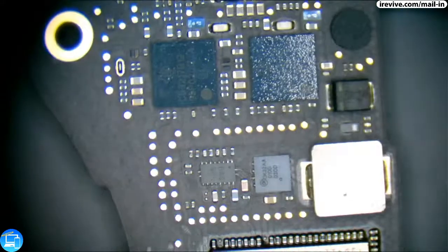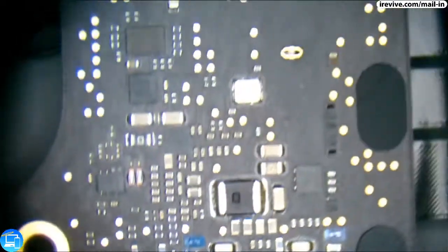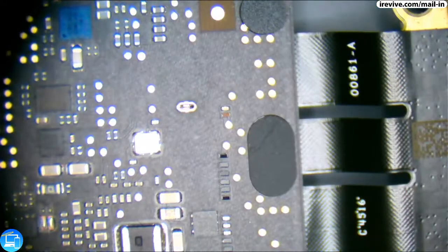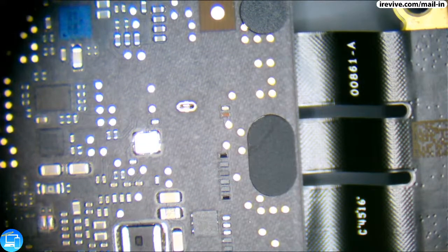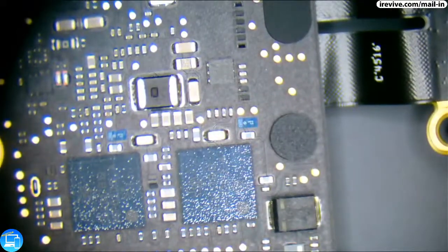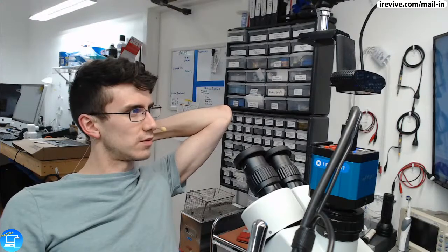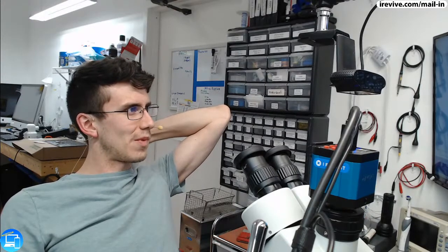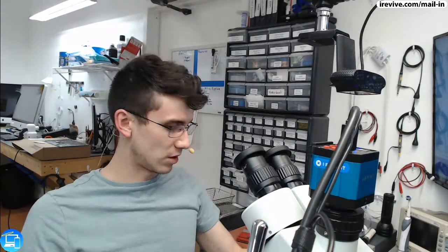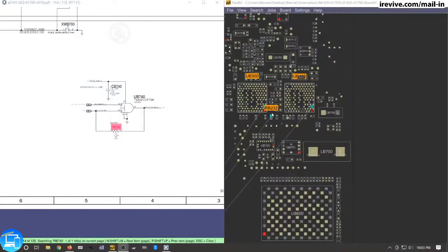All right, let's switch back over to our, I still have my microscope camera pulled up. So if you are not turning on all the way, how is it that you're getting 20 volts but still not sending an enable signal? We may actually have to check to see if all of our LDOs are present. I am going to go to logi.wiki real quick just to do a little bit of research.